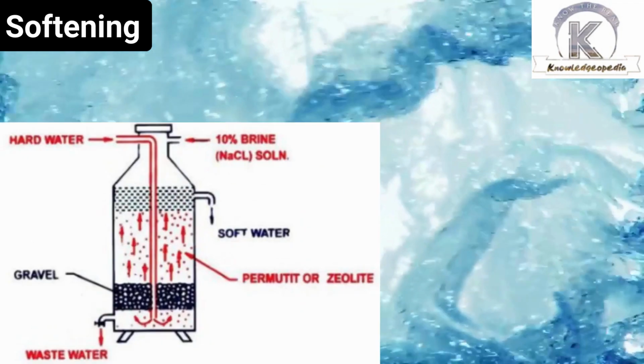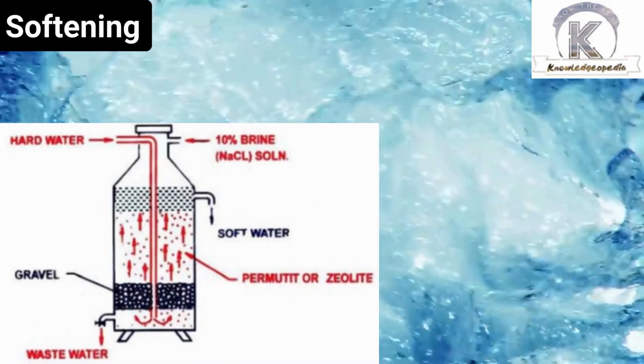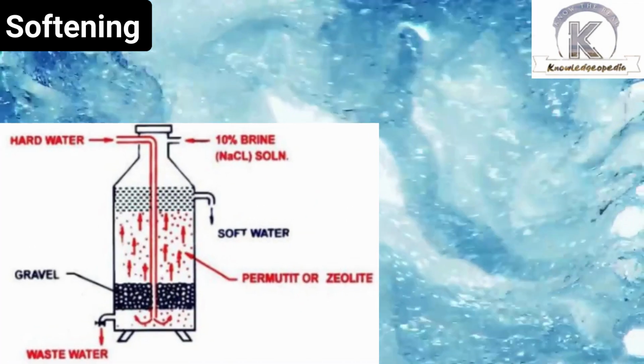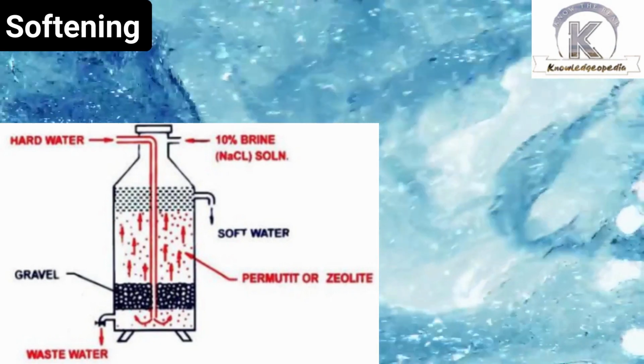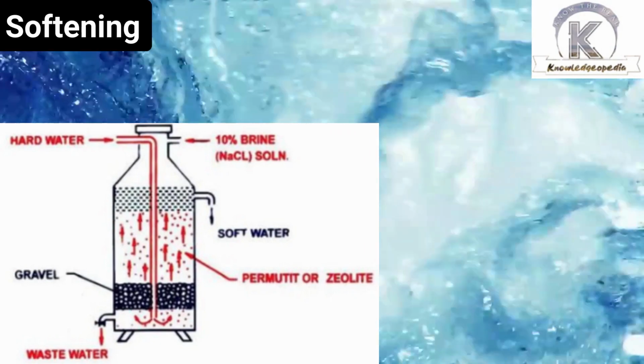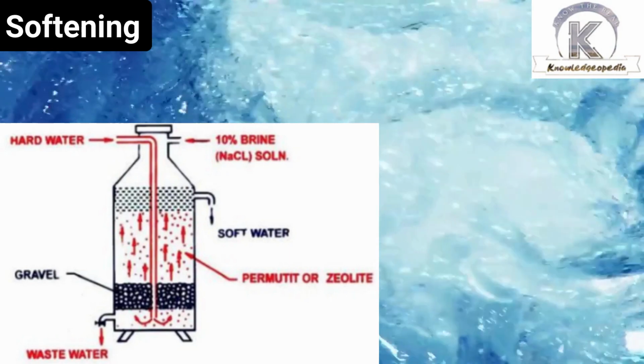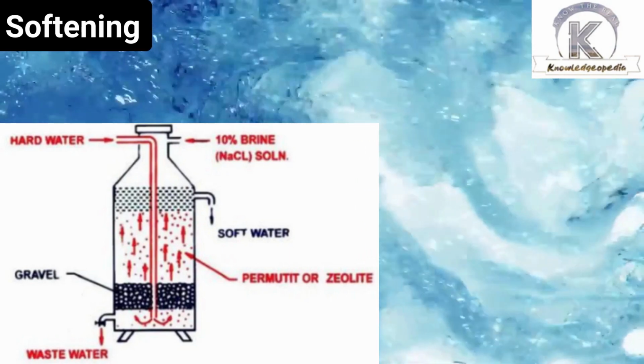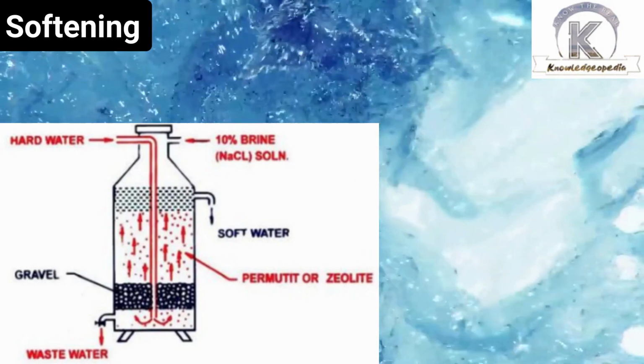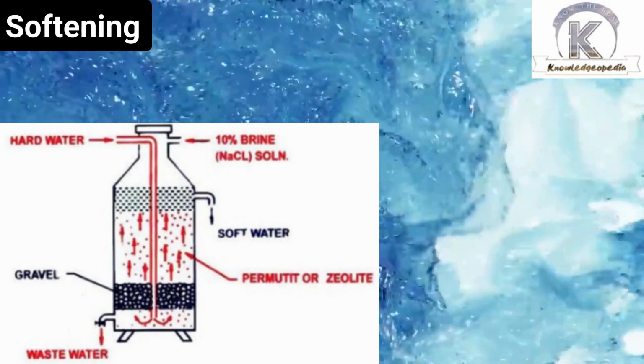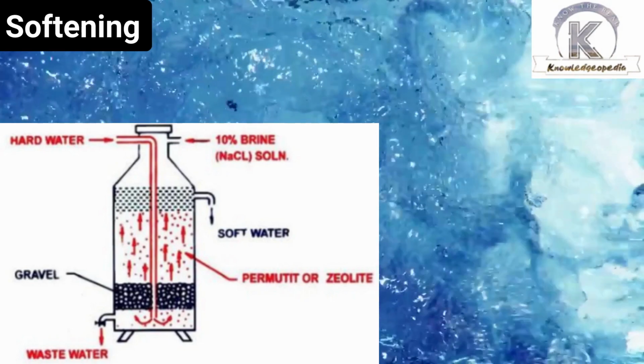The next and final step is called softening. As we observed, the build-up of minerals or scale inside pipes, fixtures and hot water heaters creates major damage to home and industrial appliances. The characteristic of such water is called hardness. When hard water and soap are mixed, the magnesium ion reacts with soap molecules and forms a solid material called a precipitate, which does not dissolve. This precipitate, or soap scum, reduces the ability of the soap to make bubbles.